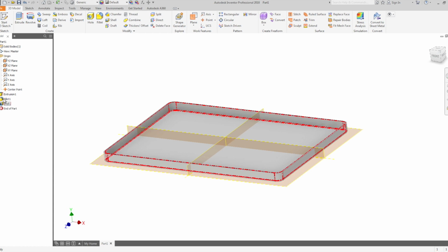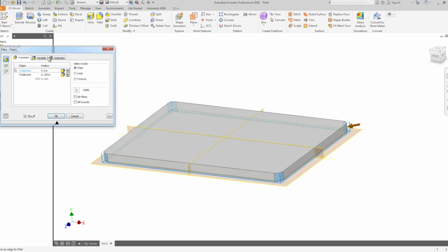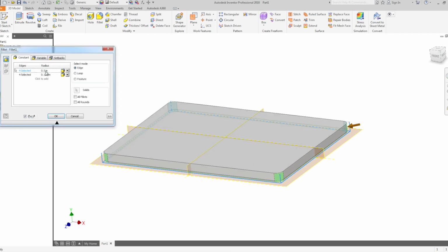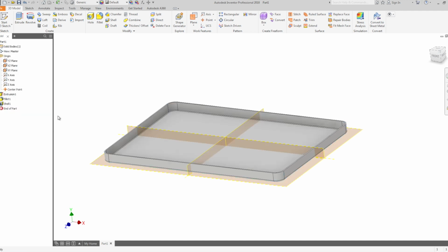like if that fillet was not good, I can just double click on the fillet. See, I just went to the model tree here, it shows everything that I just did. There's all this history of exactly what I did. You just click on the feature that you want to modify. You say, that radius, I think it's too small. Let me make it a little bit bigger. Instead of 0.5, 0.6. You just type 0.6 and hit OK, and it updates.